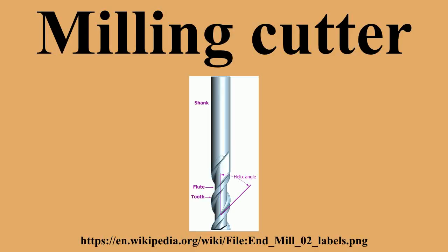Surface cutting speed. This is the speed at which each tooth cuts through the material as the tool spins. This is measured either in meters per minute in metric countries, or surface feet per minute in America. Typical values for cutting speed are 10 meters per minute to 60 meters per minute for some steels, and 100 meters per minute to 600 meters per minute for aluminum. This should not be confused with the feed rate. This value is also known as tangential velocity.